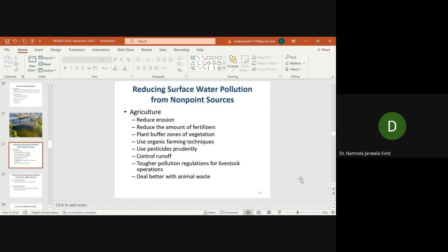Nutrients in wastewater means the ammoniacal nitrogen and the phosphate. In the wastewater generated in residential areas, the ammoniacal nitrogen is because of urea, particularly the urine. The phosphate is because we use varieties of detergents, and generally detergents and soaps contain phosphate. And mind well, treatment plants in developing nations are not designed for the removal of nutrients. At the same time, there is generally agricultural activity near the water bodies, where we use more and more fertilizers, and because of that, from the runoff we also get nutrients into the water bodies.